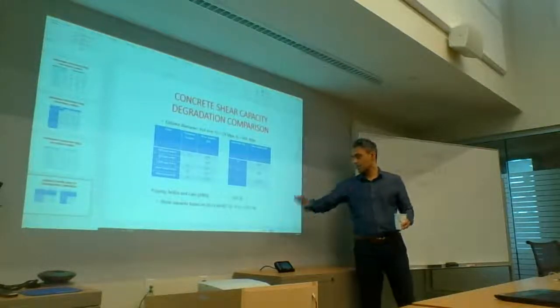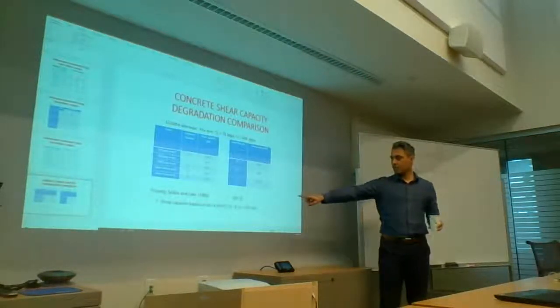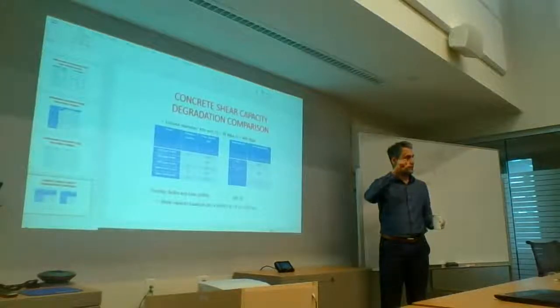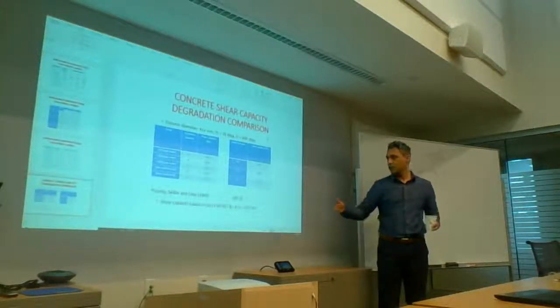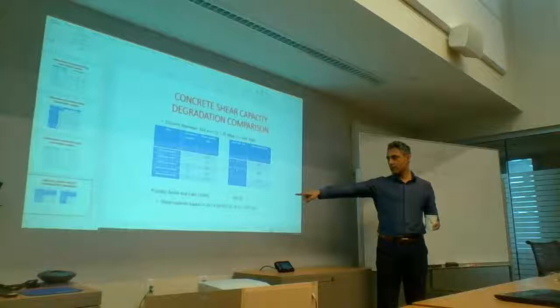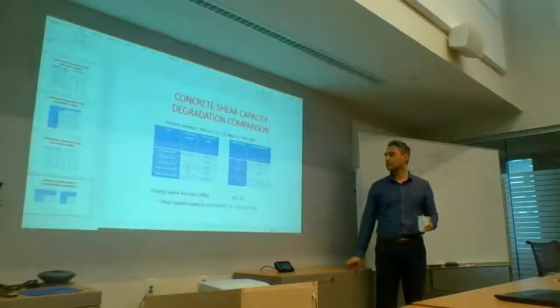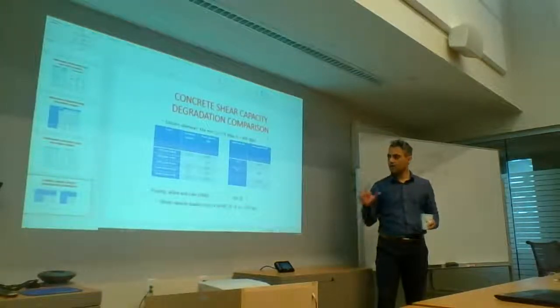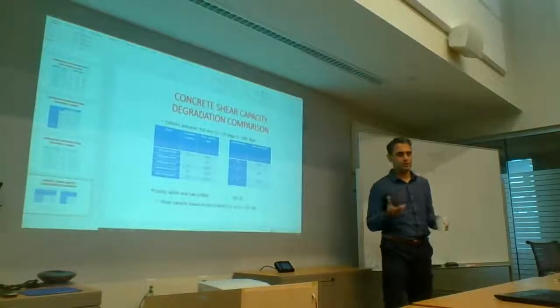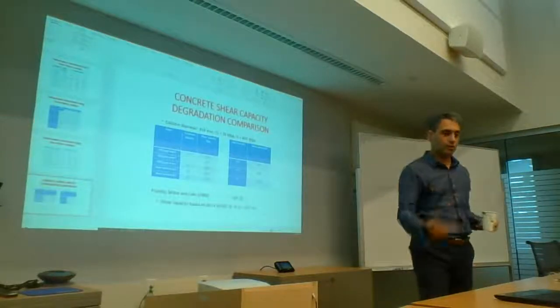Our code just has a blanket number, which says use your shear capacity formula, which has the beta and the theta, and it just says use a 45 degree for theta and 0.1 for beta, and it's quite conservative. I think now they're allowing other shear models to be used when the new code comes out.